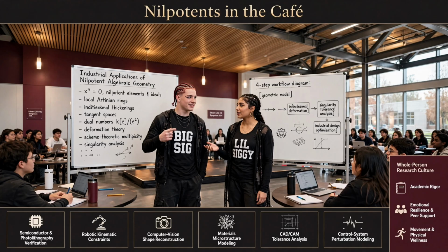The computer basically has to guess a fraction, run the physics, see how wrong it is, adjust the fraction, and repeat. Right. It's called a Newton iteration scheme. And to find the overall derivatives of the Helmholtz energy for the plant design, you need the derivatives of those monomer fractions at the exact same time. Which means tracking derivatives inside a recursive loop. Which normally breaks numerical solvers in half, but with generalized dual numbers, you simply run the Newton iteration using the dual numbers themselves. Ooh. Yeah. As the base value converges on the true fraction, the nilpotent epsilon terms automatically carry and refine the exact derivatives alongside it. It requires almost zero additional code architecture.